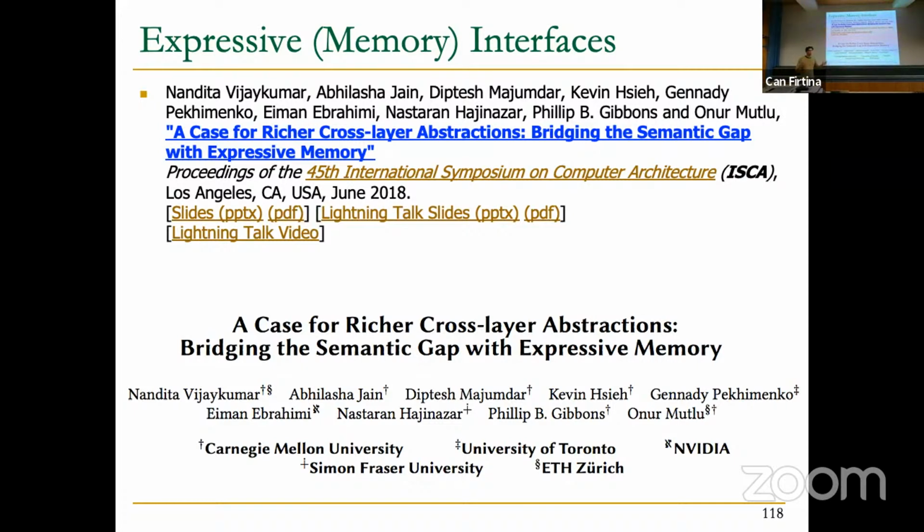You are probably all familiar with the memory hierarchy. You know that there is a main memory, and closer to the processor we typically have cache memories and registers, and you might have heard of a technique called prefetching, for example. What is prefetching? When the processor needs to access data, in reality it reads the closest level, which is typically the L1 data cache. But the data originally resides in DRAM.